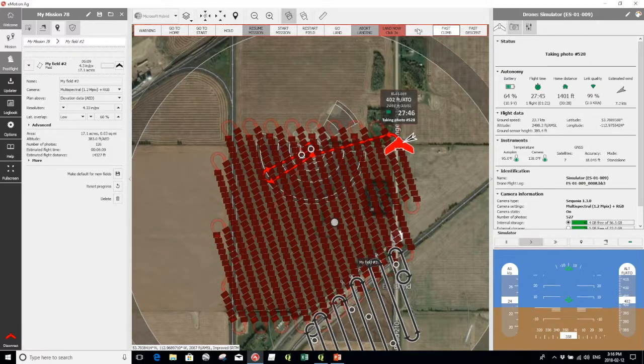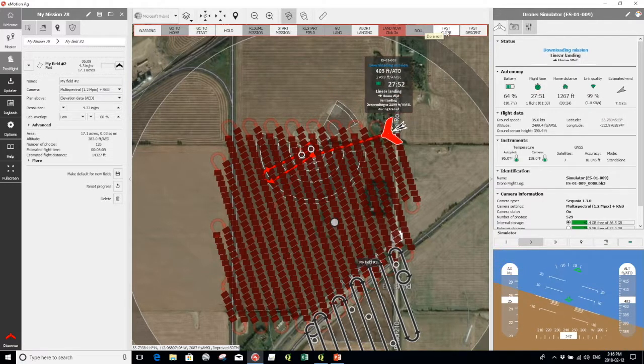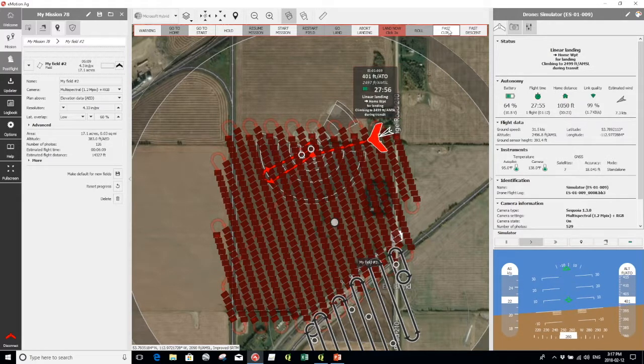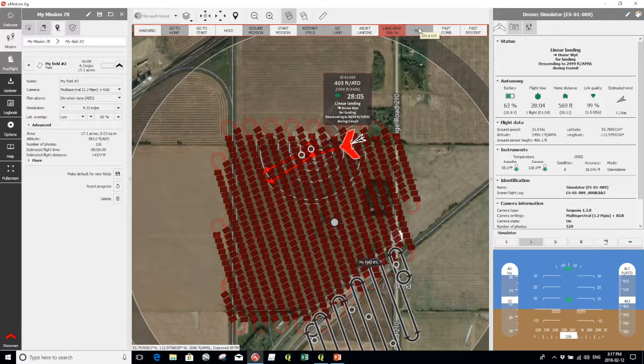These are evasive maneuvers. They're designed for if you're getting bird attacks or something like that. You can either do a fast climb, a fast ascent, or a roll. Going to home waypoint for landing. A fast climb is actually the most effective maneuver for a bird, because a bird can definitely dive. They'll dive after you. Or a roll, I mean, it might scare them off, but other than that, the fast climb is definitely the best option.